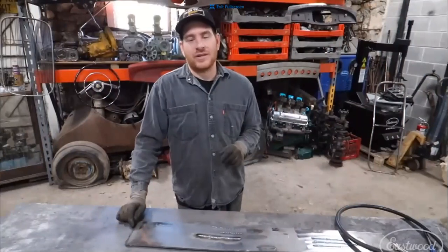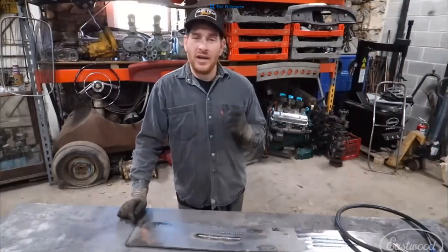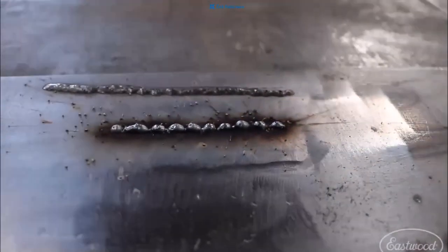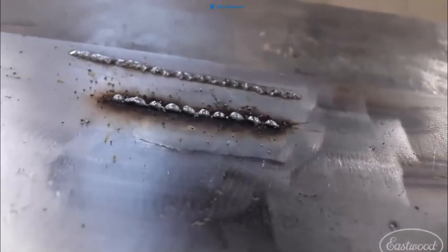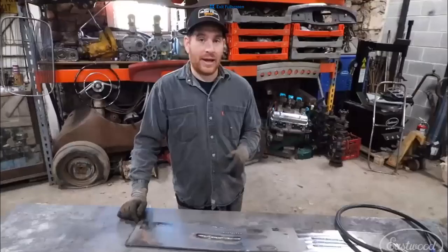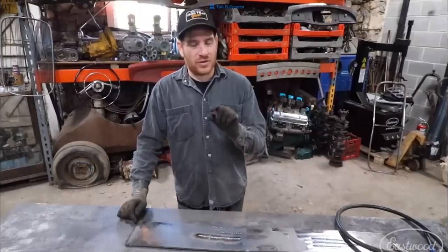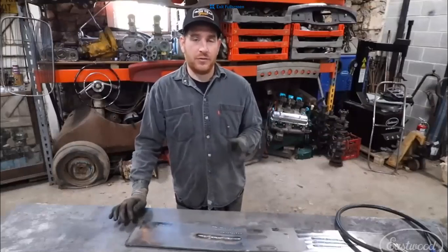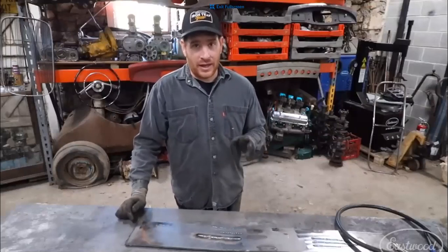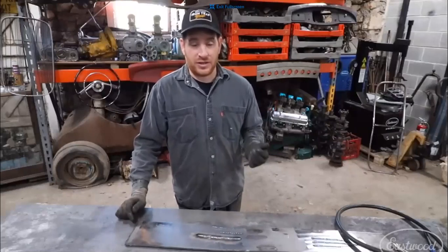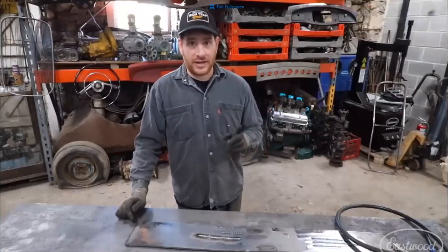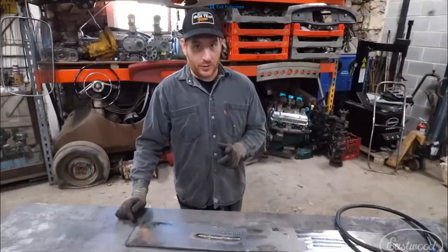All right, second reason that your MIG welds might suck. If you're having problems with your welds sitting high atop the metal that you're welding, where they may just knock off easily with a hammer, we have little piles of welds with a gap in between them. There's a few things that can cause that problem, and usually one of these is what causes the issues when I see that. So the first thing is simply the settings on your MIG welder.